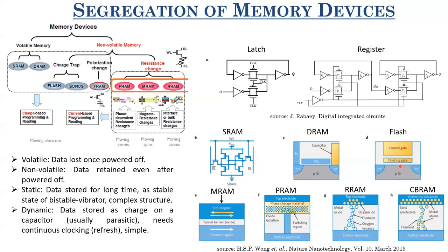So since there's an inherent charge on this ferroelectric material, you assume that there would be a threshold voltage shift. Now the best part about this ferroelectric material is that it's polycrystalline. And in polycrystalline materials, we know that there are several domains, right? There are several grains, and all those grains are separated by grain boundaries. So in these polycrystalline materials, which these ferroelectric materials essentially are, each of those grains has polarization pointed in a certain direction, and that is random.